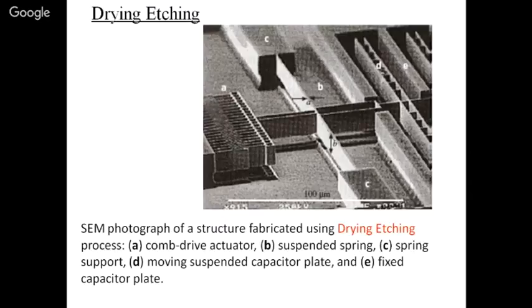The scanning electron micrograph of a structure fabricated using dry etching. Comb drive actuators, that is very important. Suspended spring, spring support, moving suspension capacitor plate, fixed capacitor plate, all can be manufactured.